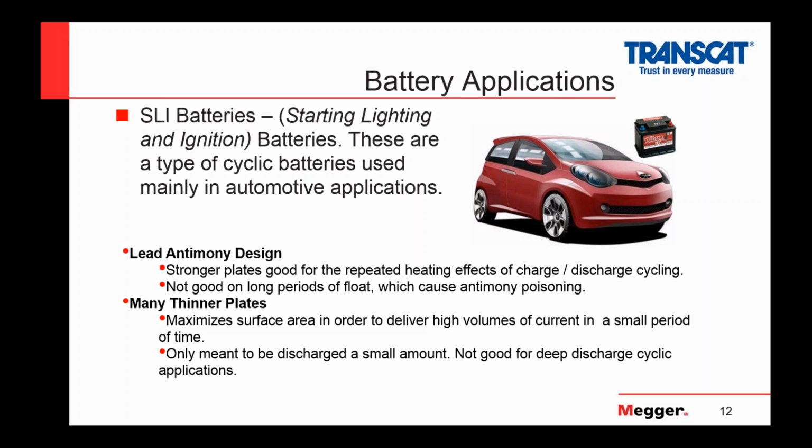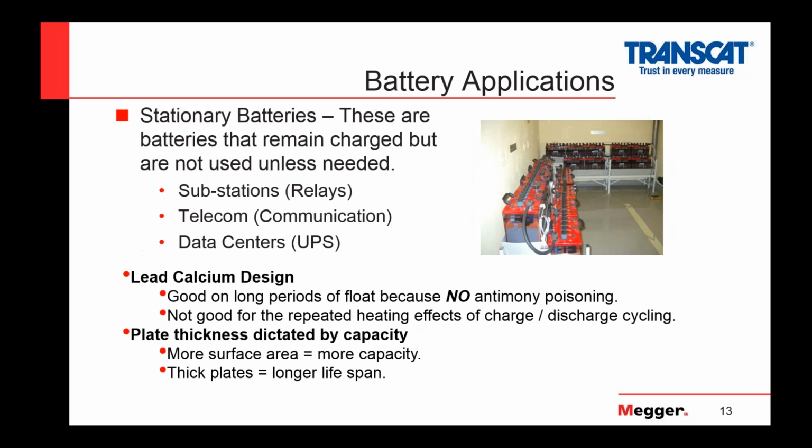In fact, it's dangerous to leave it like that because these can form dendrites, which I'll cover in failure modes, but actually can lead to fires. So again, we want to pick the right battery for the application. This is why I never use a car battery for a stationary application. They're not designed for it.